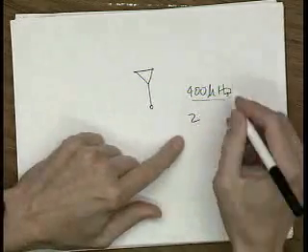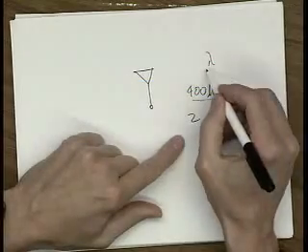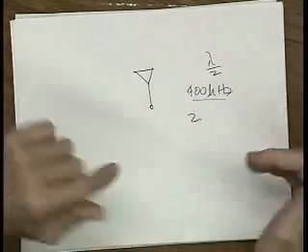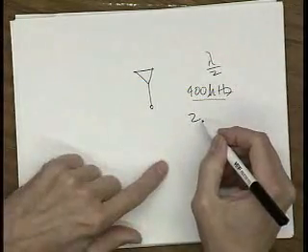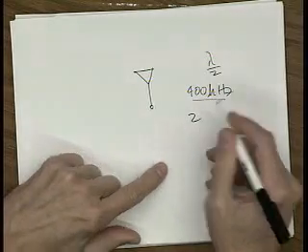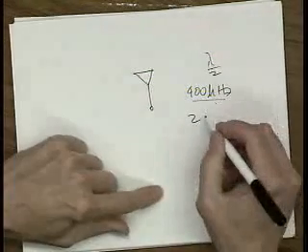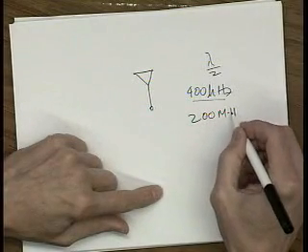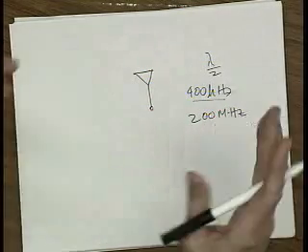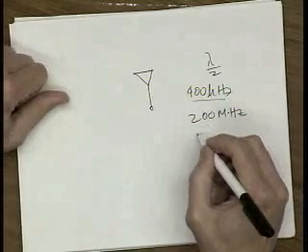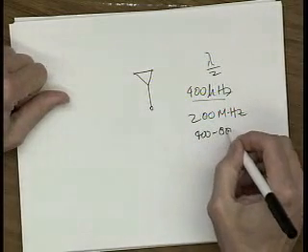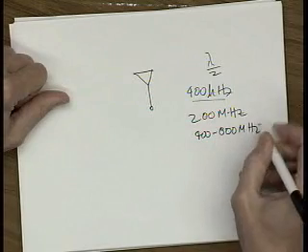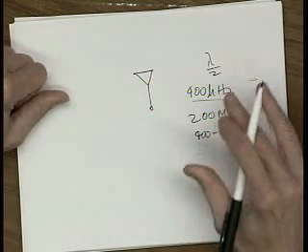The best antennas are about half a wavelength long. The size of TV aerials run at a couple hundred megahertz, that kind of number. The UHF antennas, which are the smaller ones, are around 400 to 800 megahertz. We call these kinds of frequencies RF frequencies.